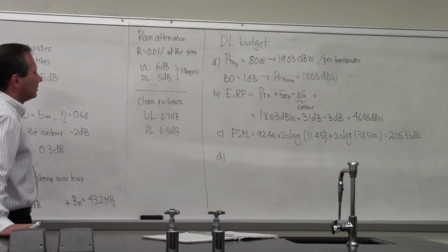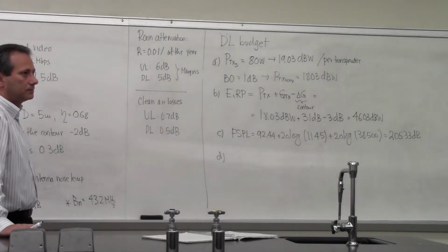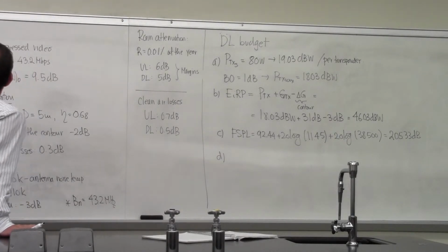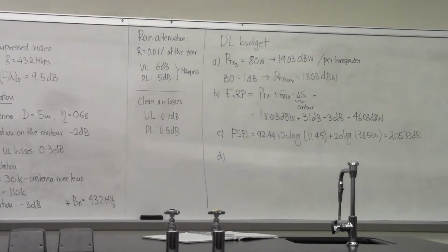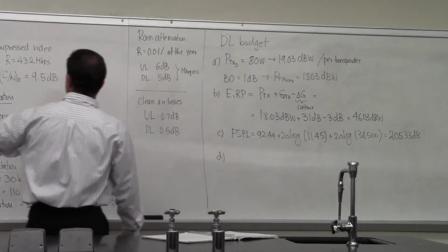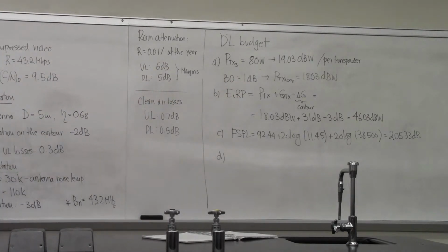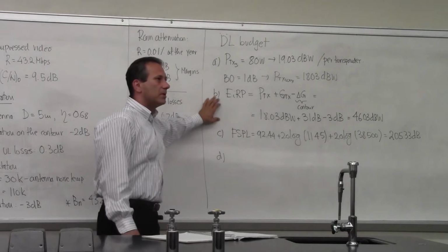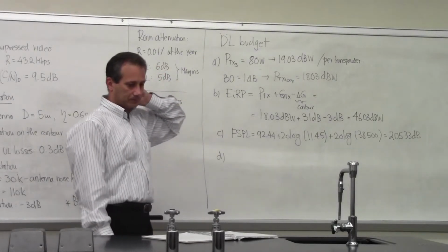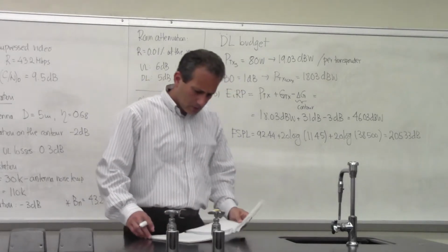So for the entire satellite, it would be 28 times. 28 times this 80 watts. Would that fit in a total power budget on the transponder? We need to check that. But you do calculations per transponder, right? And you assume that each transponder is the same.